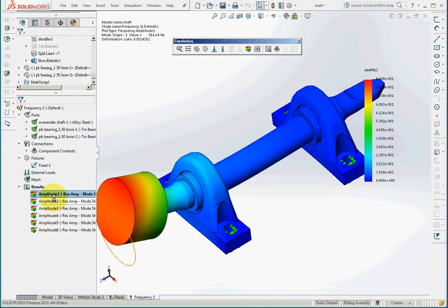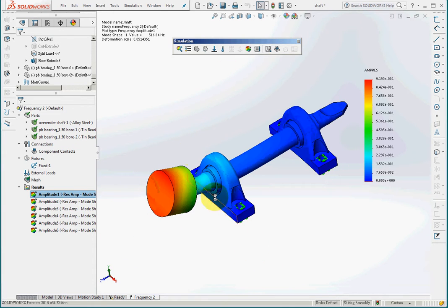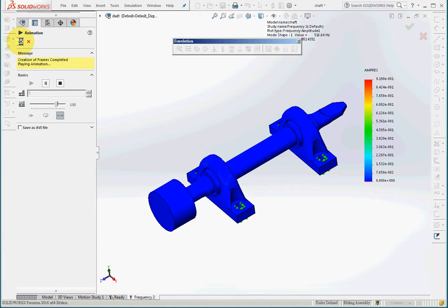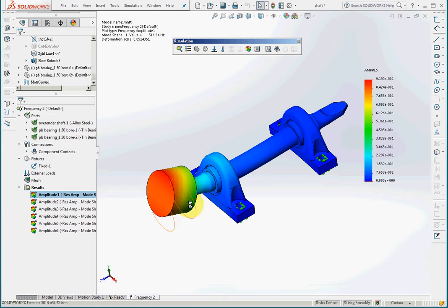This is the result. For example, now in the first mode, the frequency dropped from 1300 to 500. So there's a significant drop in natural frequency. So it is important that you bear in mind that an increase or decrease in mass will affect the natural frequencies.